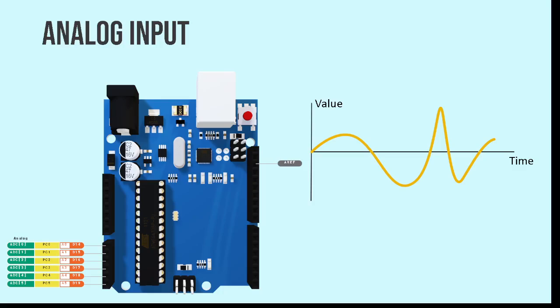In the code, you can reference them by A0, A1, A2, A3, A4, A5, right? Those are the same names as in the Atmega, right? In the Atmega, in reality, we have 2 more, but they are not present in the Arduino, okay? So if you program the Atmega, you have 2 more there. In the Arduino, they are hidden because they are used for communication when you upload the program, right? But you have 6, okay? You cannot connect analog signals here. You can connect them, but maybe you will burn this or you are not reading anything, okay?